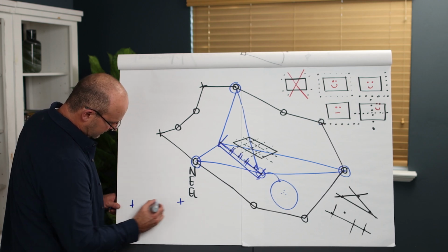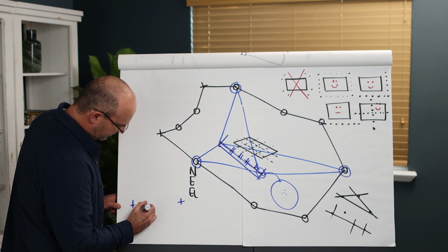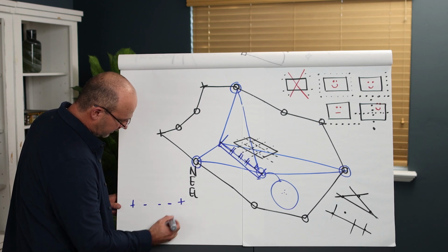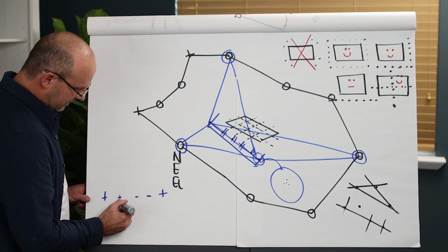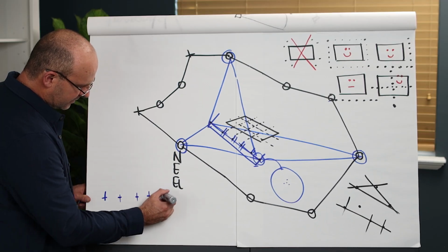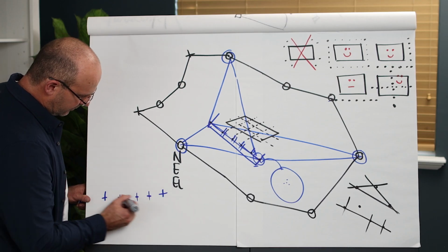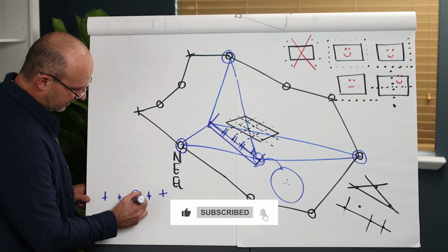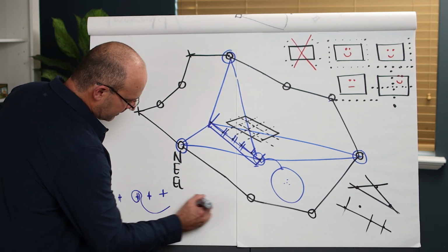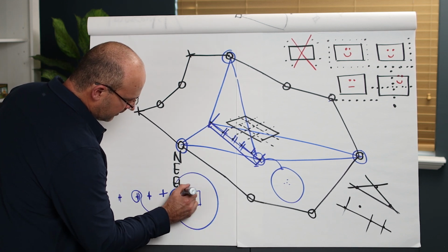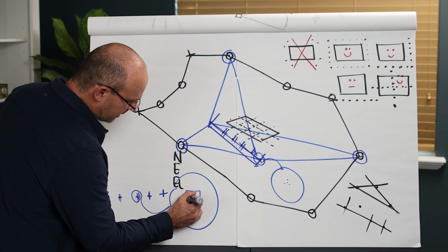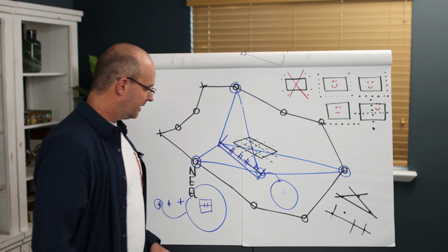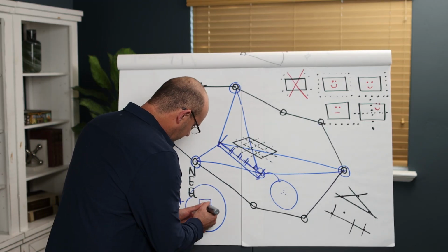I will set up backsite, and I will pound a hub and mark a line, mark a line, mark a line, and then I will shoot a distance and shoot a distance and shoot a distance. Then I'll set up here and backsite here, confirm the line, and then shoot a distance and shoot a distance and shoot a distance. If I zoom into this, it will look exactly like this. It'll show, here's my hub, and here's my line, and I'll see a line and a line. Why did that happen? That's the instrumental error again. The point is right in the middle.